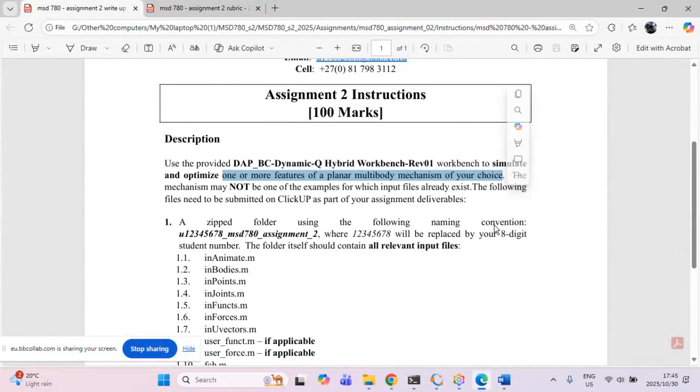So you can choose if you want to use a single design variable or multiple design variables in your system. Regardless of that, my focus in this case will be more on validation of the optimization that you performed. A good validation would be to start with a single design variable. If I have a single design variable, I can set up just a linear graph of the design variable ranging from, let's say, 0 to 100.